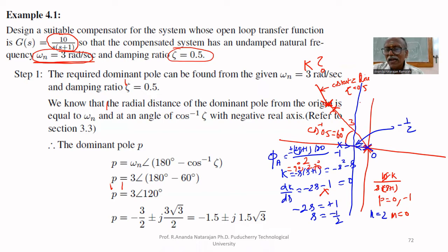One goes at an angle of 90 degrees, and another goes to infinity at minus 270 degrees. Where is sigma A? Sigma A equals the sum of real parts of poles, that is minus 1 plus 0, minus the sum of real parts of zeros, which is 0, divided by 2. That is equal to minus 1/2.